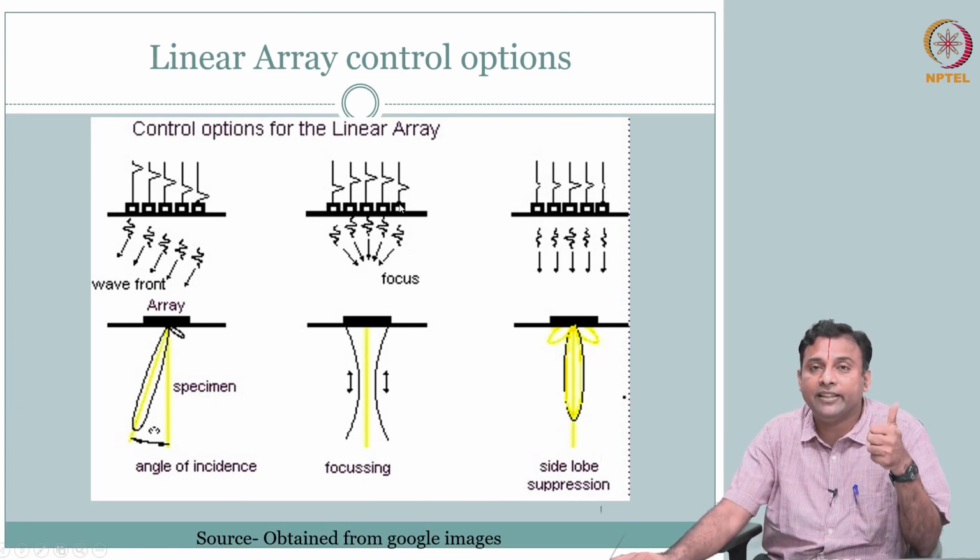So the advantage is that now I don't need a physical lens. All I need to do is manipulate the time delay when I excite each crystal. If I play with that, I can get focus wherever I want, however tight I want to focus. Everything can be manipulated by manipulating the sequence of excitation.